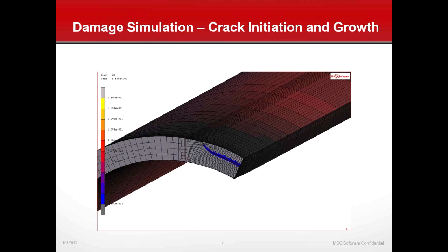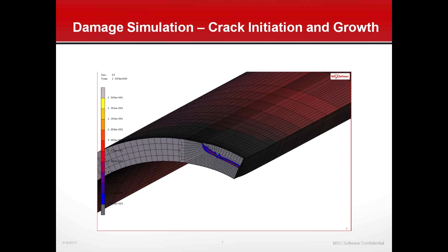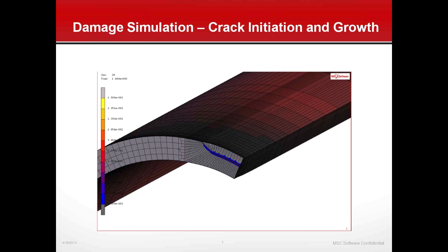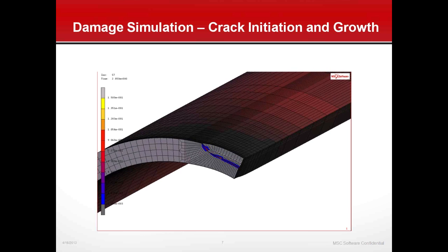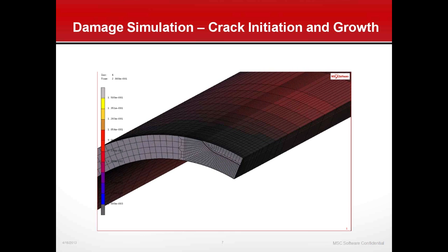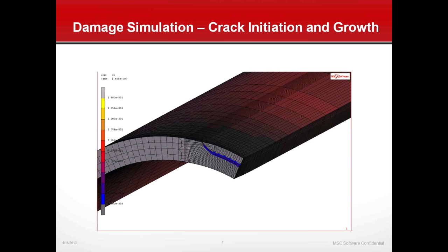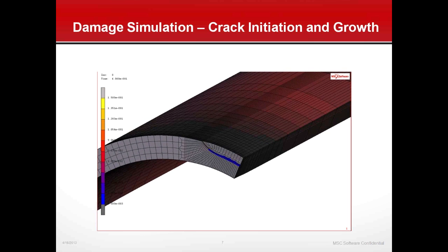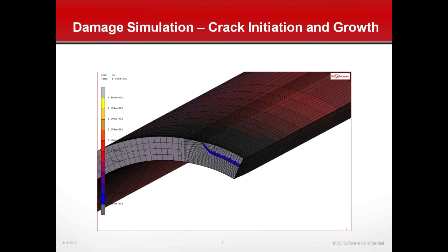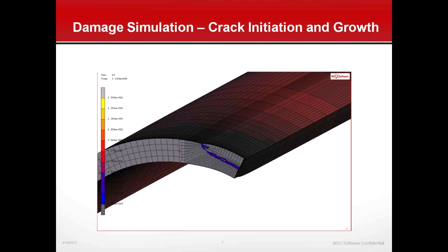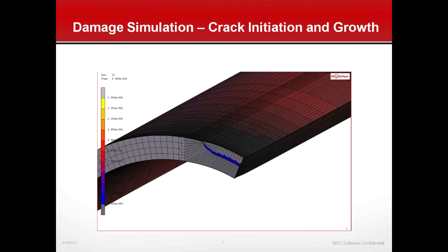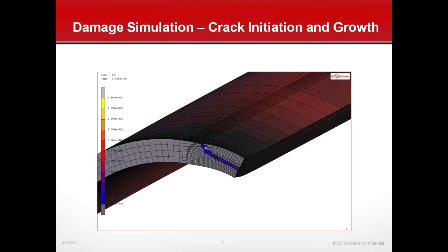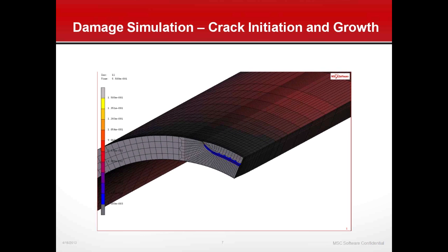Here's an example where we have a crack which is initiated and it's growing by means of the damage model. So you start out with a surface crack and it grows, and the purpose of this exercise, from what I understand from the one I got it from, is that they want to try to determine the fracture mechanics quantities based upon this damage model. And they combine it here with element deactivation when a certain damage level is reached, so you can expand the crack.